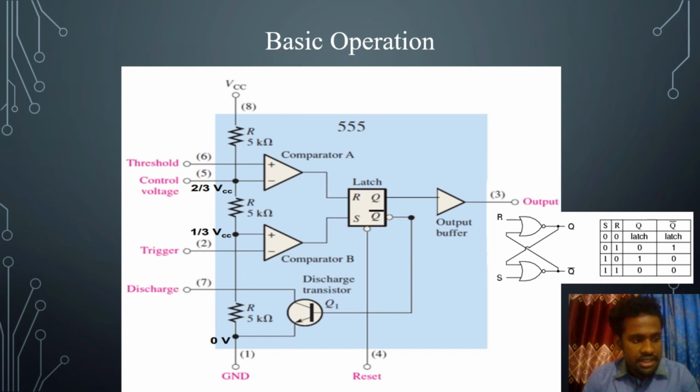And here we can also see two nodes. In these two nodes, the voltage is divided. At the first node, there are two resistors from this node to ground, so 2R divided by the total resistance 3R, multiplied by the input voltage, gives VTH, which is 2/3 VCC. At the second node, there is one resistor from this node to ground, and for this we get 1/3 VCC.